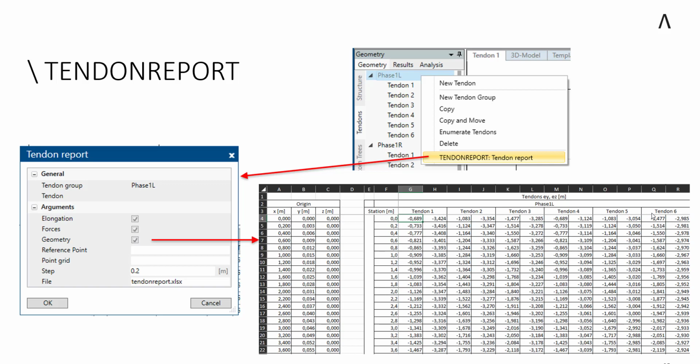So each tendon shows the station plus a Y and Z center relative to this origin point. By this, the geometrical location of the origin, but also of each tendon, is directly in there. If you want to have the XYZ of the tendon, it's also very easily possible. Just go on the right side, add one column where you add up the Y values and Z values, and automatically you have the XYZ for the tendon purely.